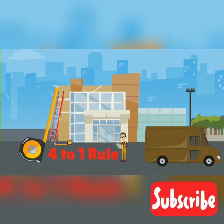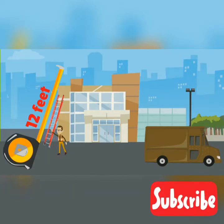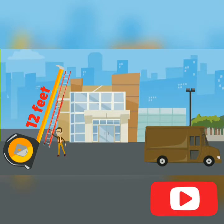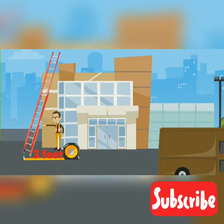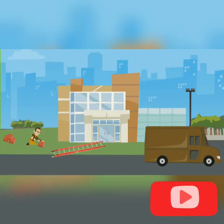Angle the ladder properly by using the 4-to-1 rule. The bottom of the ladder should be 1 foot away from the wall for every 4 feet the ladder rises. For example, if the ladder touches the wall 12 feet above the ground, the feet of the ladder should be 3 feet from the wall. Make sure that both feet are securely on the surface. Don't place a block under one foot if the surface isn't level.